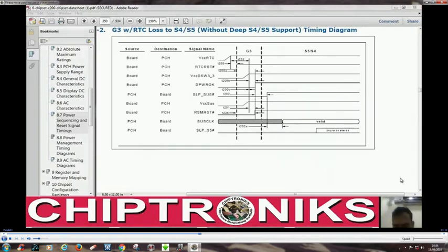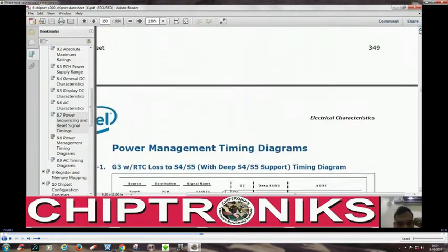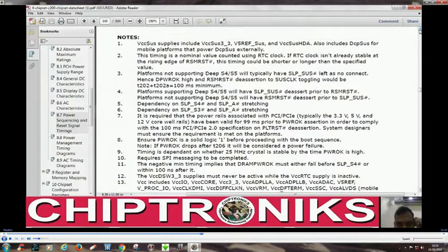Now we have already seen how the deep S5 section is generated. Now we'll see how VCC_SUS is generated. After SLP_SUS, S5_ON has been released by the IO controller, and hence the motherboard has reached the S5 stage. So now the board will supply the VCC_SUS power to the PCH, but as we have seen, VCC_SUS includes three kinds of voltages: VCC_SUS3, V5REF_SUS and VSUS_HDA. So let's see all of them.